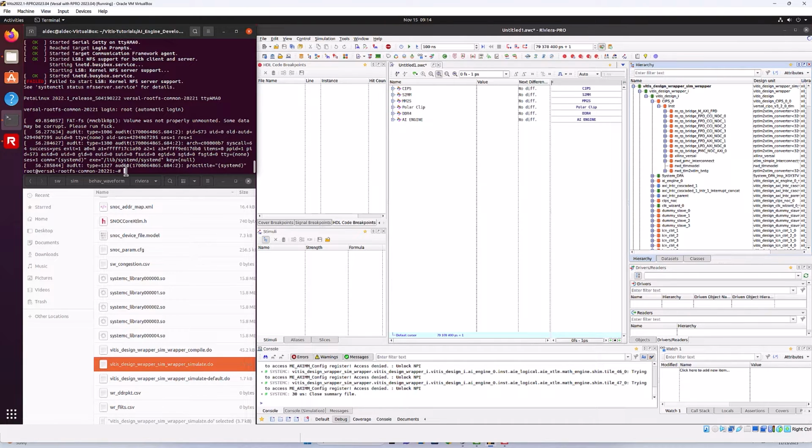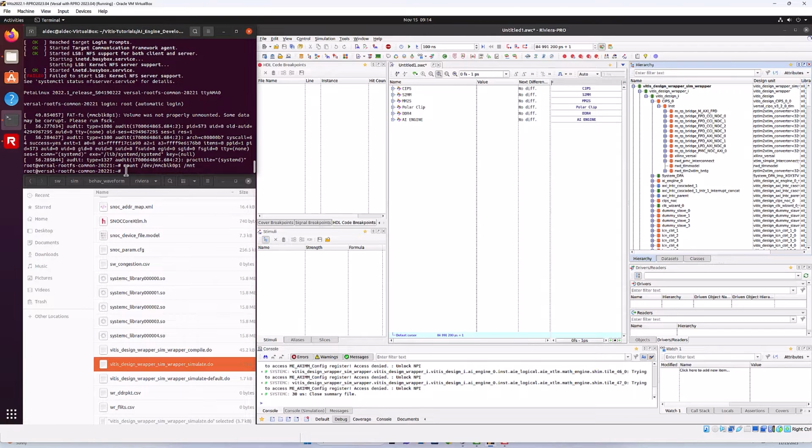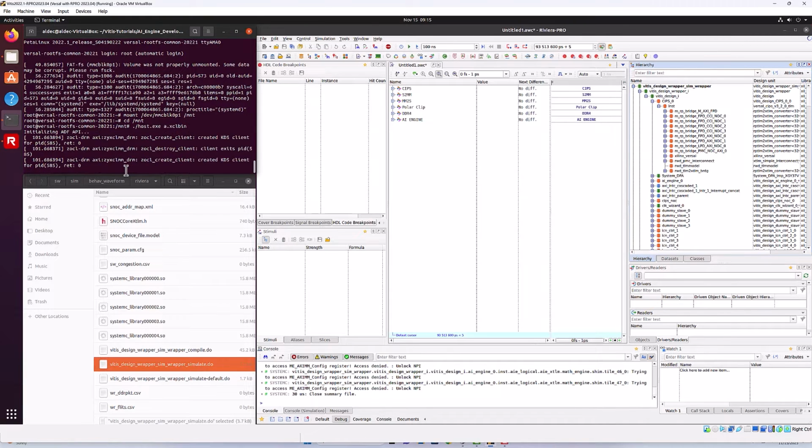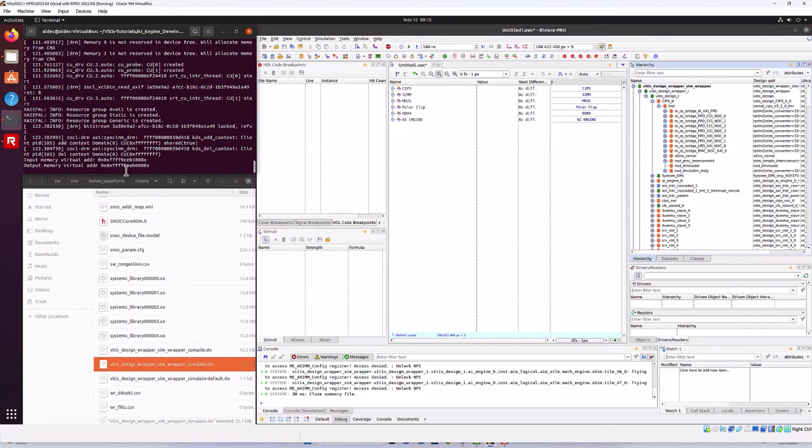So the command is mount. cd to this directory here, and then let's go ahead and run. Okay, so what I did there is basically just run the application with the FPGA's device image. So host.exe is the application, and then the XCL bin is the device image, okay, with the bitstream and all of those connectivity there.